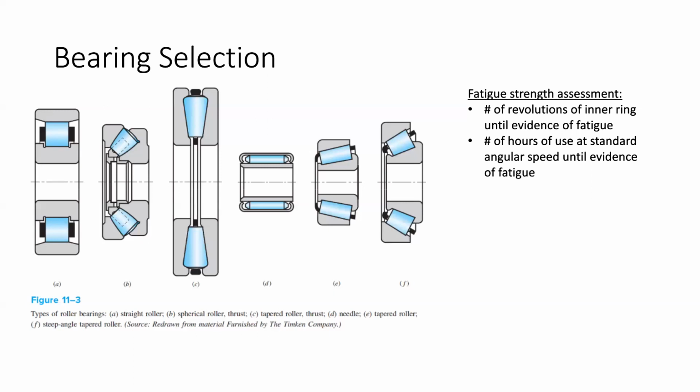So it's a combination of the best of both worlds, right? You have the small amount of tolerance so that you can do press fits. You don't have over-constraint in your bearing. And then you apply a small amount of load to get rid of that play. Typically that's commonly done with fasteners, right? Imagine I have a fastener that pulls one material this way against the inner ring and the opposite direction against the outer ring. That's what you call an axial preload. Bearing operation is really sensitive to how you axially preload it, so it's important to design your joint interface to provide the correct amount of preload.